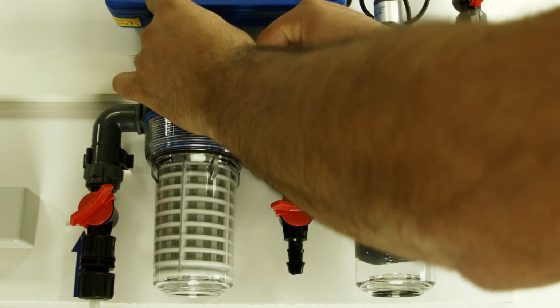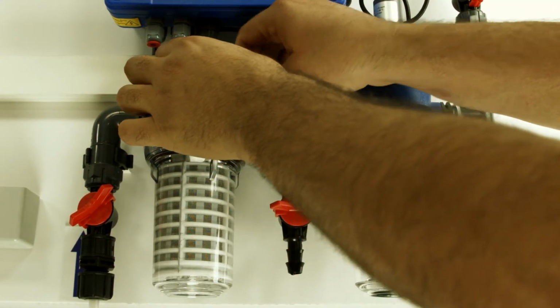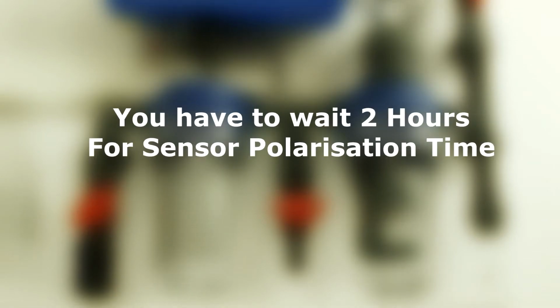Connect the sensor cable to the Omnicon and wait 2 hours. You have to wait 2 hours for sensor polarization time.